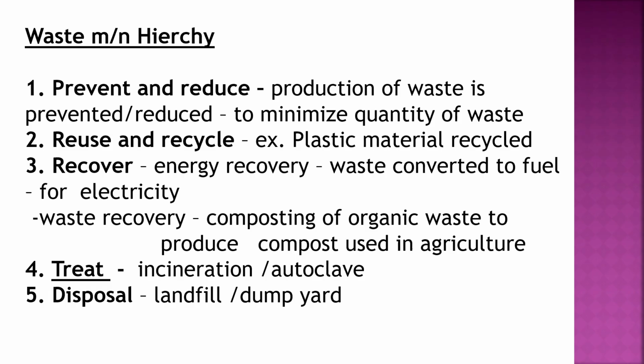Then treat. So whatever leftover waste that cannot be reduced, cannot be reused, cannot be recovered should be treated properly to prevent health hazards. So the treatment, for example, incineration or autoclave, and then disposal. So that should be disposed properly in landfill or dump yard, so that the public or society should not get harm from that waste.